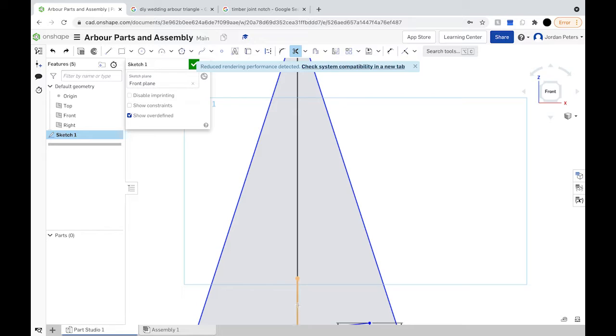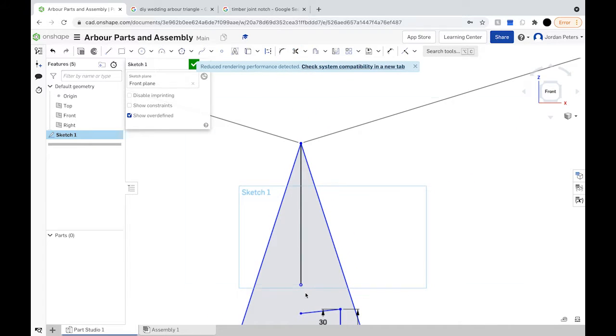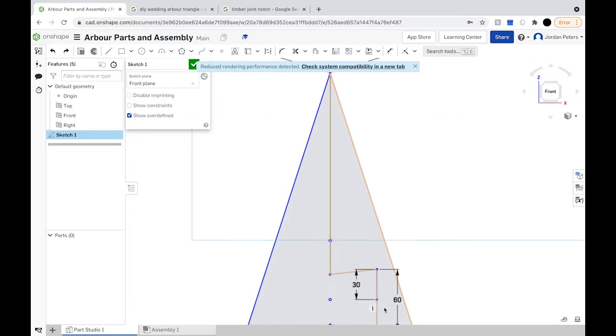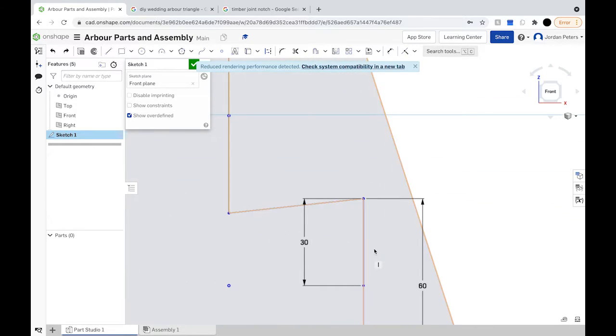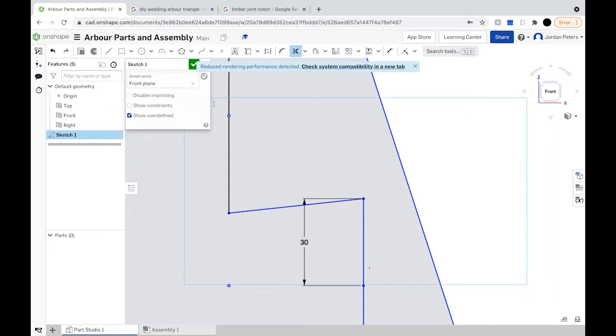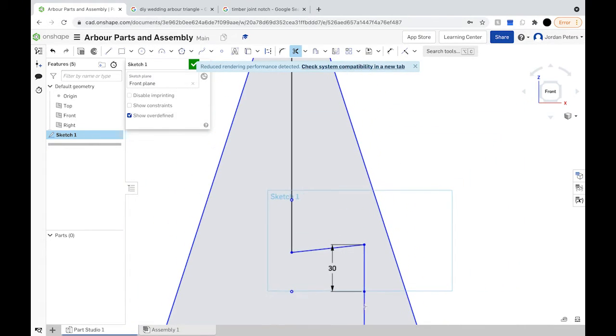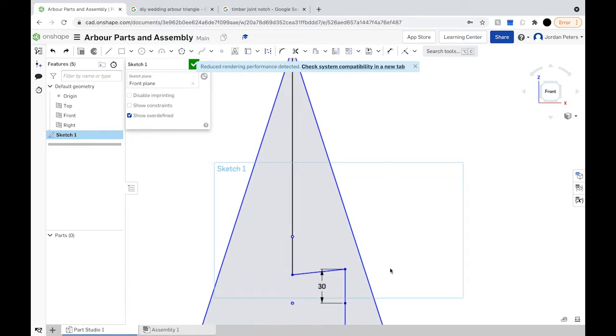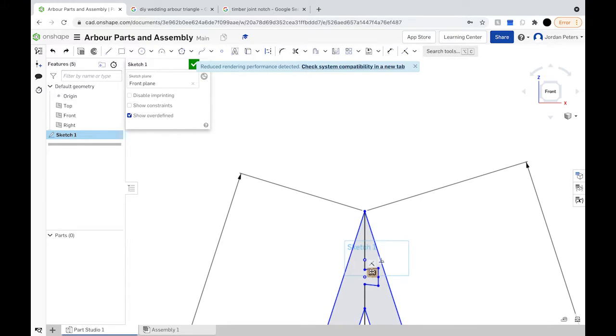Reselect the scissor tool, left click, and Ctrl Z. Alright, so now we have single lines, which is what we need later on to extrude it. I believe there was one more here that we need to get rid of. So back to our scissor tool and left click, and we'll just for good measure go through and make sure, yeah, so those are single lines, which is all good. Alright, now we have our notch.